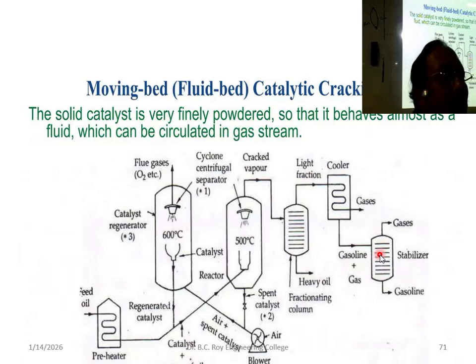And why does the noise happen? You have to understand the mechanism of petrol burning. There are 4 steps. First is intake, then compression, then power stroke, and finally exhaust stroke. Intake means it is taking in. After that, compression, pressurization of the fuel, and then the spark plug will ignite.